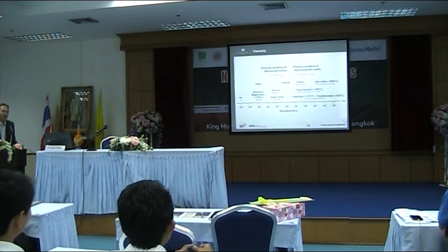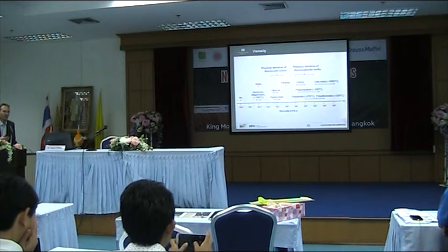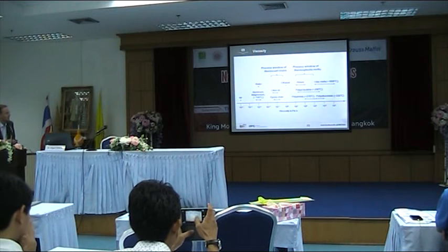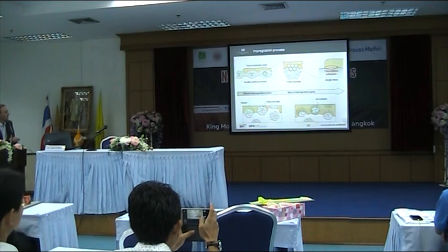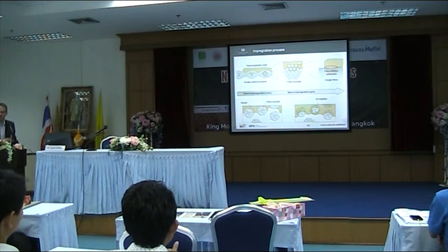It's much higher, and you need much more pressure and much more time to get the melt to flow into a textile prepreg. You see here, the problem we have with the impregnation is to get the thermoplastic melt into the textile prepreg.